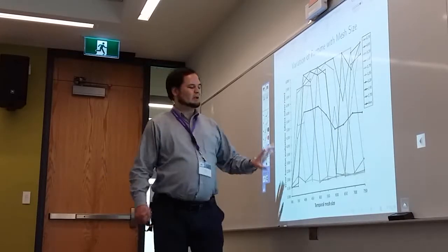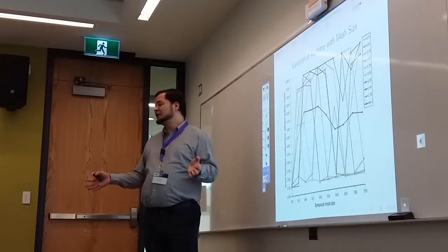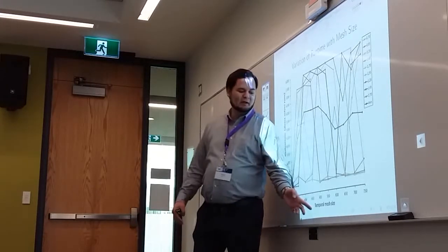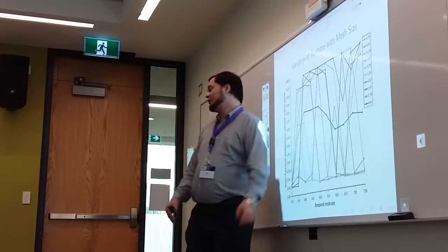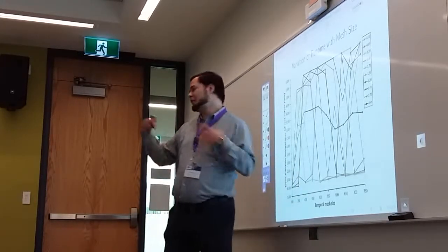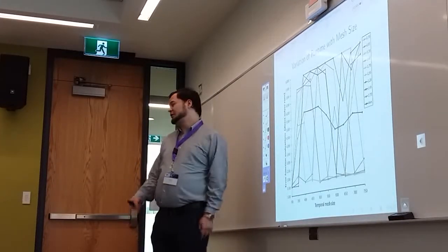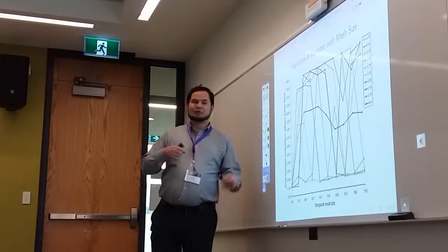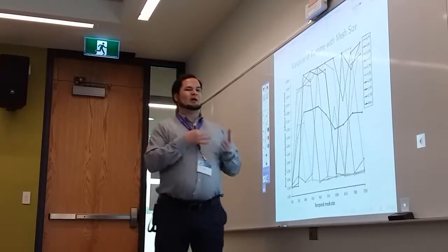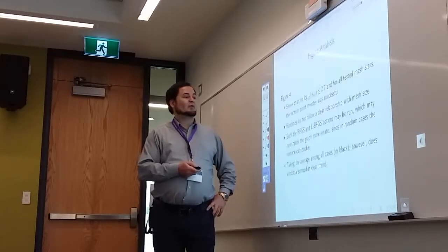An important point to make is that runtime doesn't significantly vary with the change in the mesh size. For low mesh sizes, between 500 and 2000, we can easily vary the mesh size and the runtime won't change significantly. So we shouldn't be shy about giving the algorithm a higher mesh size.